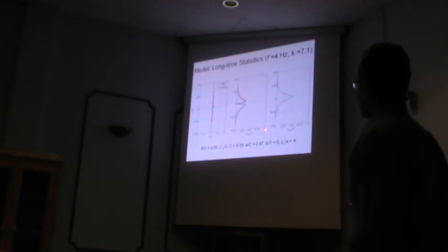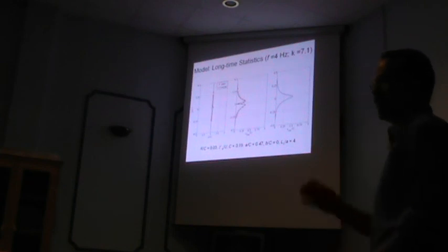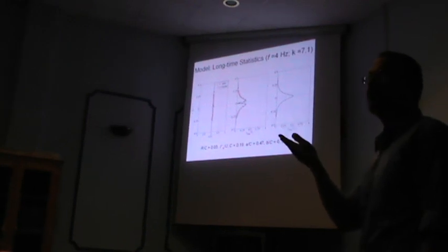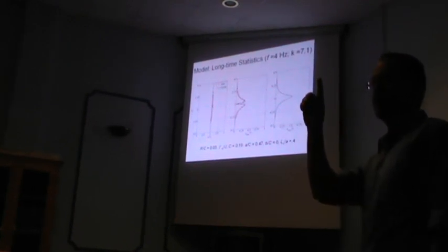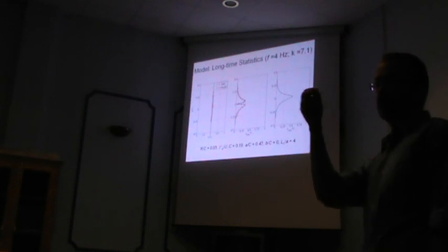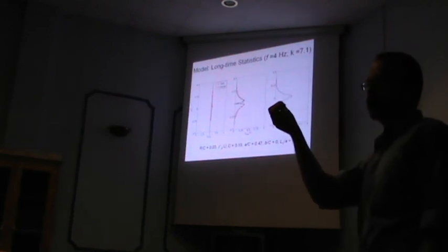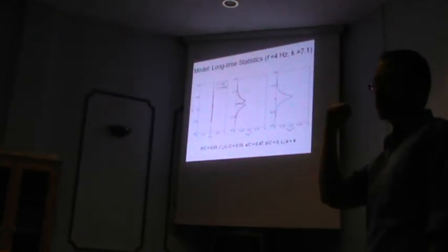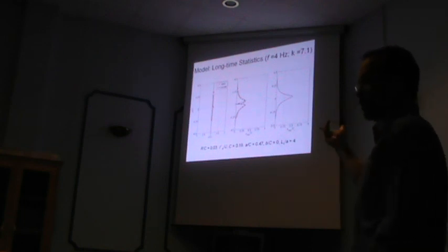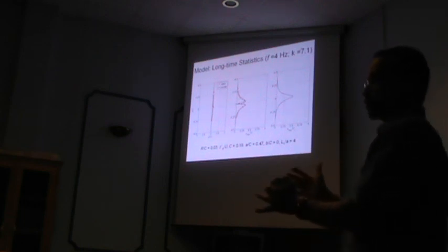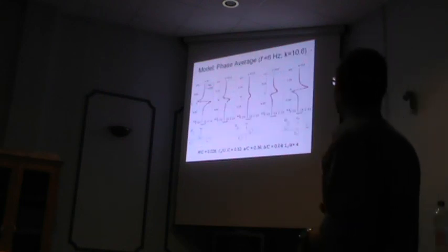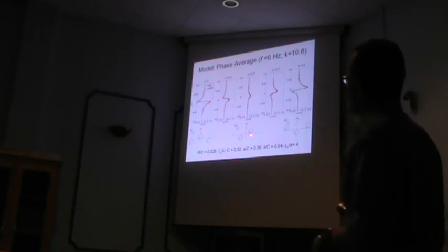And the one advantage of the model is, in fact, if you have only single velocity measurements and you can reproduce the velocity with this good accuracy, you can use this model to extract the cross-stream velocity component. So if you don't have full-field measurement capability, you can do individual single-point measurements in this kind of problem, and use a model like this, if the flow is organized and dominated by vortex structures, in order to extract the other missing velocity component. Similarly, we compare with the highest frequency case, which